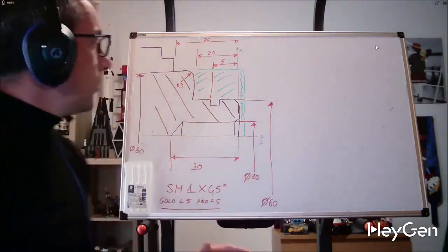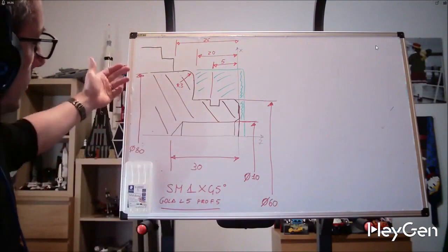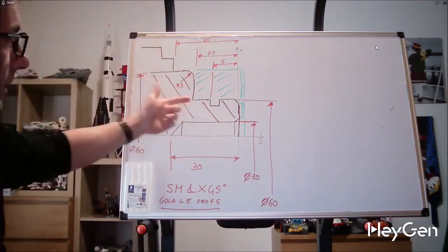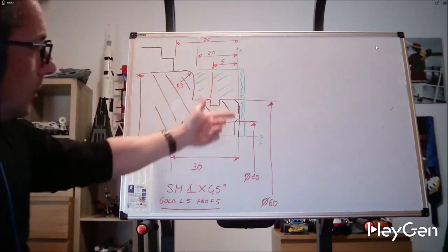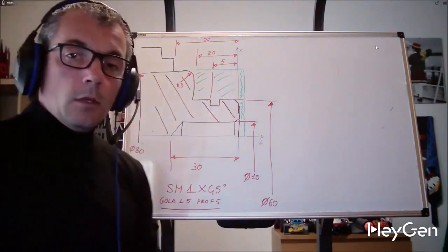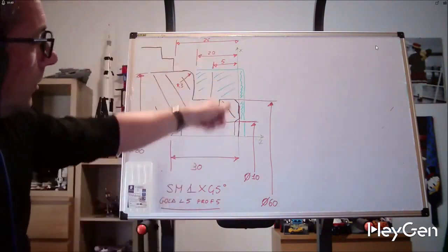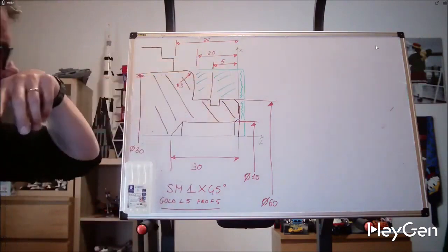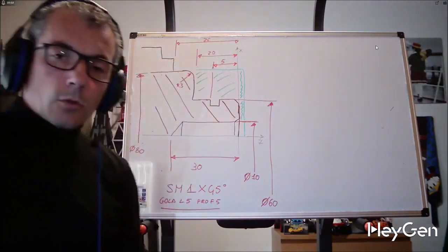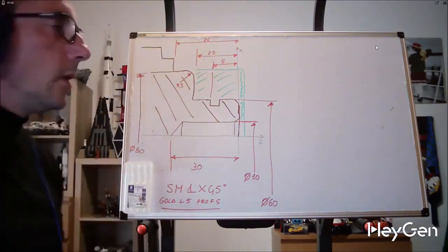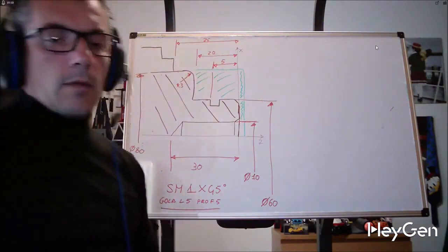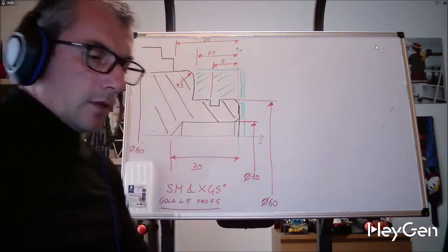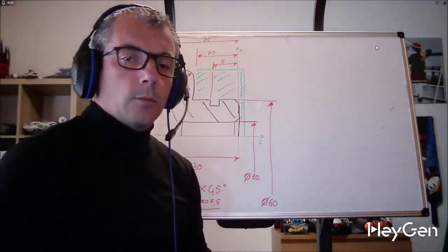Regarding how to manage ourselves, let's assume a metal piece, diameter 80, to be brought to this drawing with 1 mm excess material on the face. So we will need to face it, hollow it out, drill, and make the groove. The order of operations will then need to be optimized based on the turret, the operations we need to perform, and the type of finish. Let's not worry about that. Let's focus on making a small program.